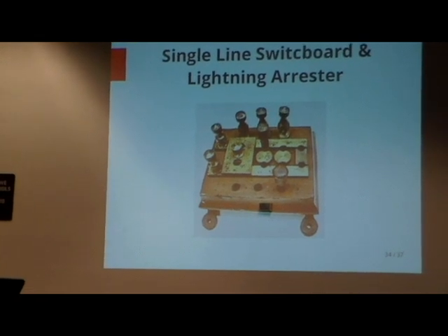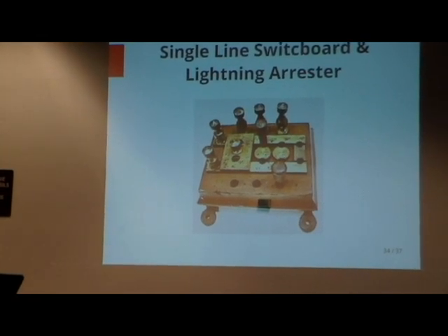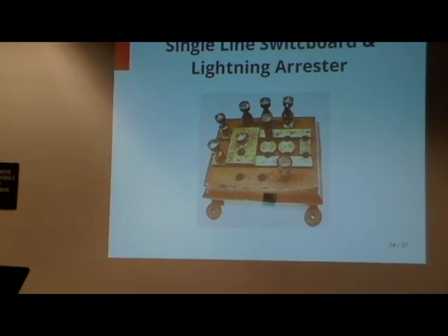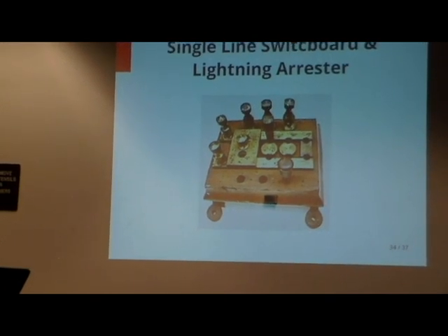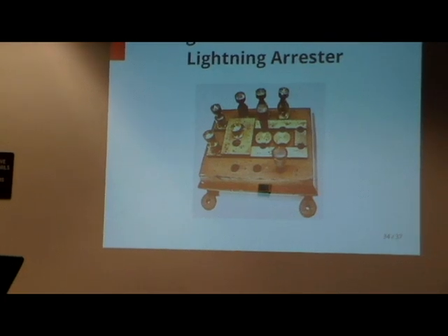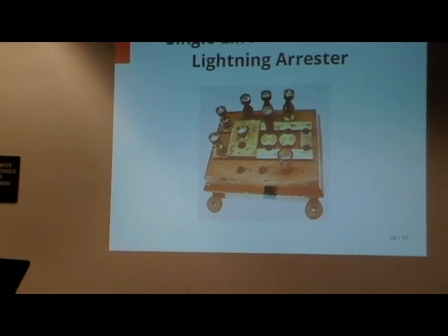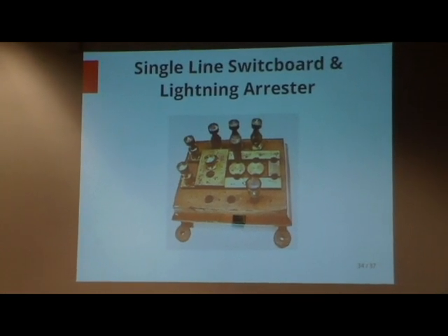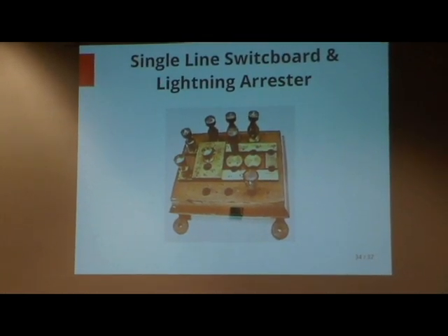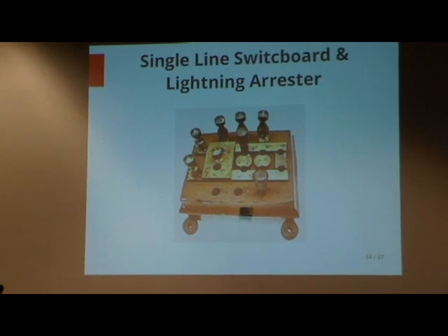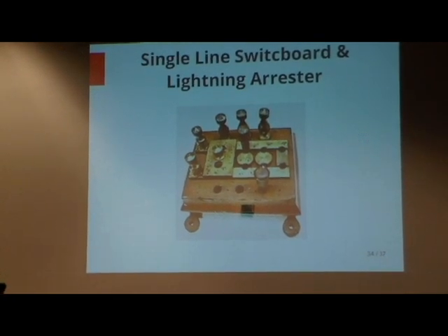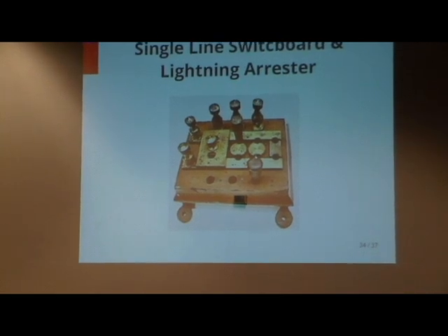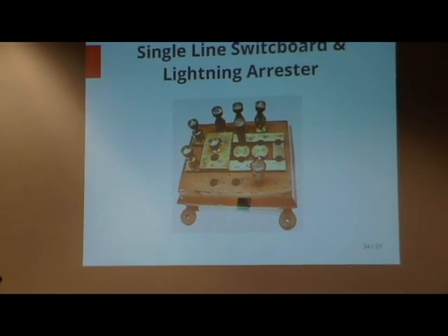Each of these buttons, or circular plates, is for these wire binding posts, and those were for the inside loop of the office. The inside loop would be terminated on them. And whether or not that insulated loop would be connected would depend on the placement of the brass pegs. You can see one of them's in place, but this one would need to be in place here to connect the inside loop to the line on both legs, okay?